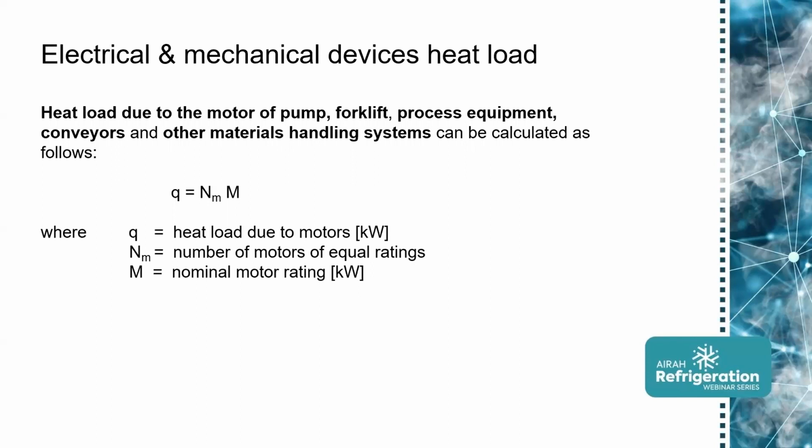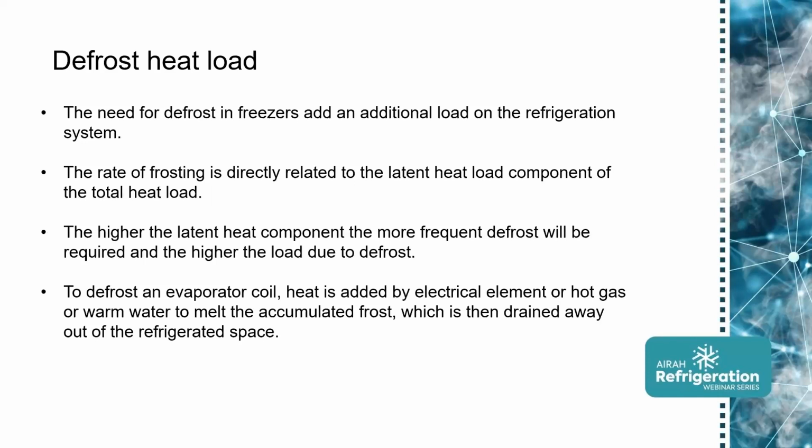Next one, Marie. Now, the last one is only applicable to freezers, because in freezers there is a need to defrost evaporators. Defrosting evaporators using some heat source will impose an additional load on the refrigeration system. The rate of frosting on the evaporator is directly related to the latent component of your total heat load.